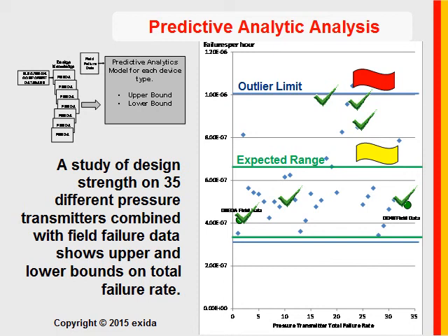So, how do you find or validate failure data for valves that are not SIL certified? Well, even valves that are SIL certified, you take a look at other numbers and compare. You can do your own data comparison, and you can see all the FMEDA certificates on the FMEDA website in our Safety Equipment Reliability Database.